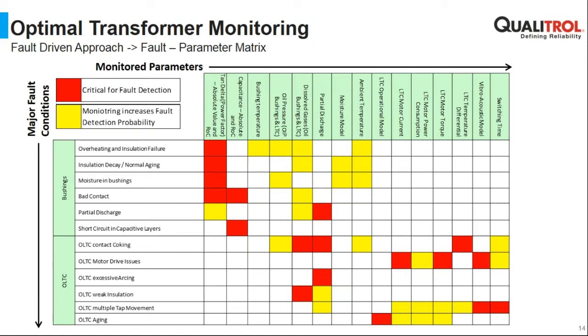You're just removing the output. And if you want to look at how the failure developed using a DGA, of course you're setting everything back to zero, and that means you don't see the development of that fault. So there are some pros and cons.